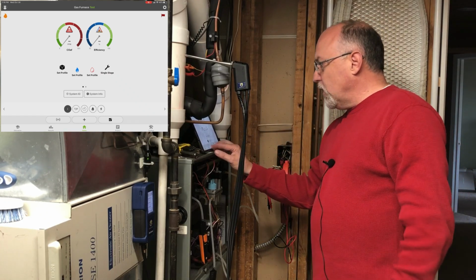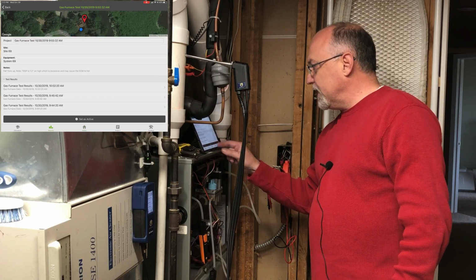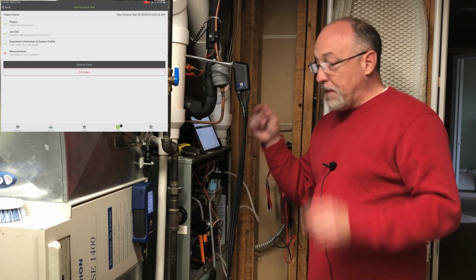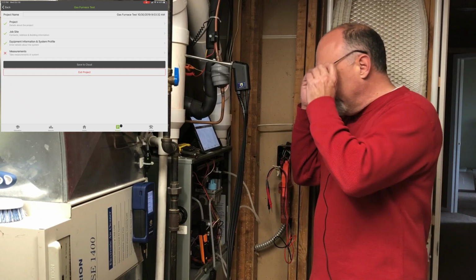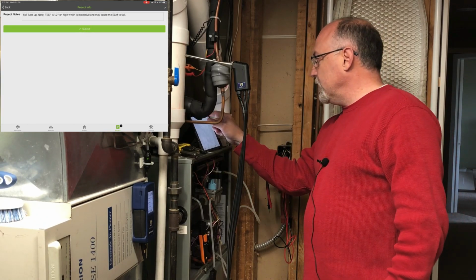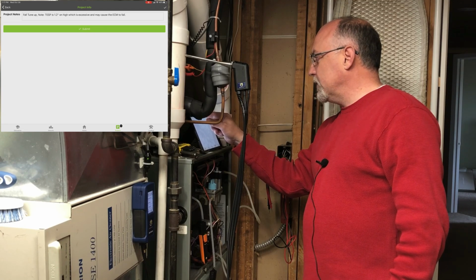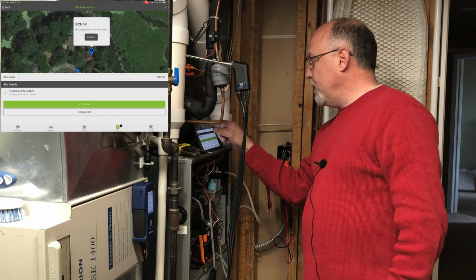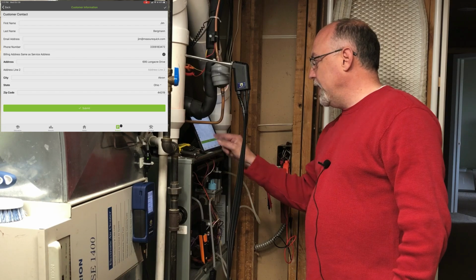So I'm going to go in my results tab because I've done my furnace before, and I'm going to go ahead and just set this project as active. And now I'll go into the project, and you'll see that my project, my job site information, my equipment stuff's already all done. So I go into the project details. You can see I marked it. My external static pressure was high when I did that. Job site information, I got the house marked. I've got the address all in and all ready to go.